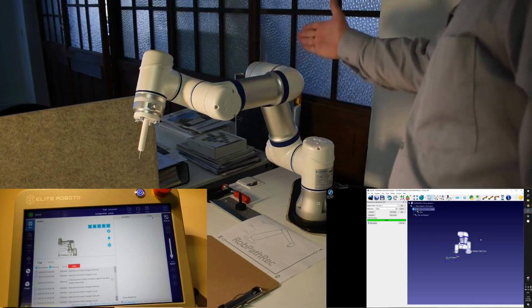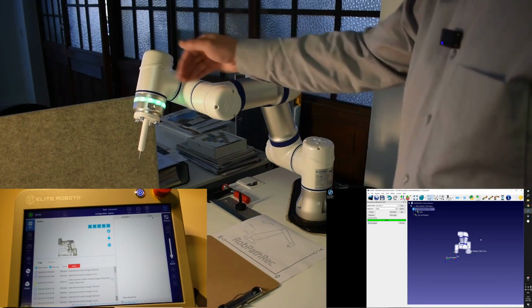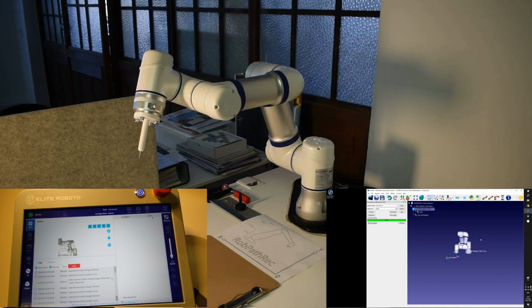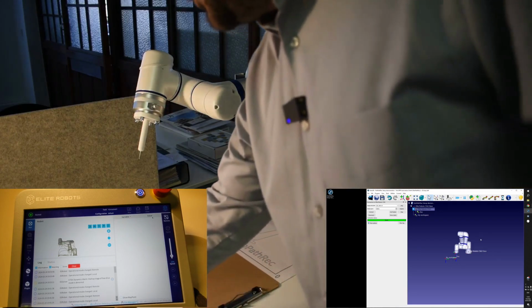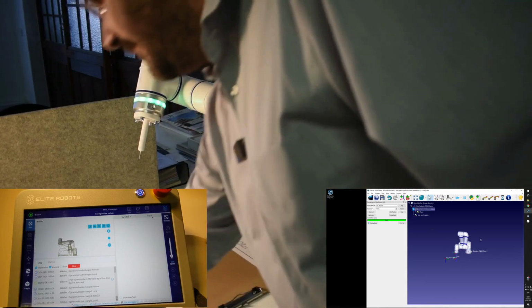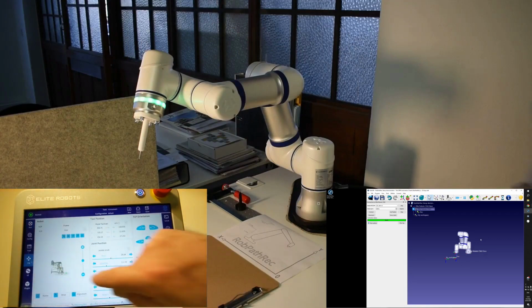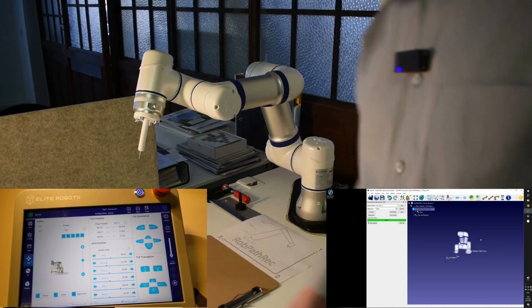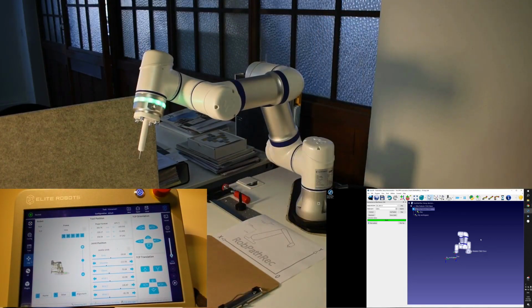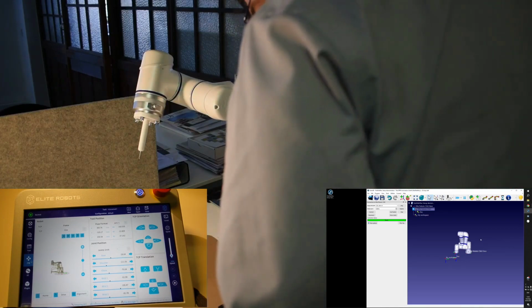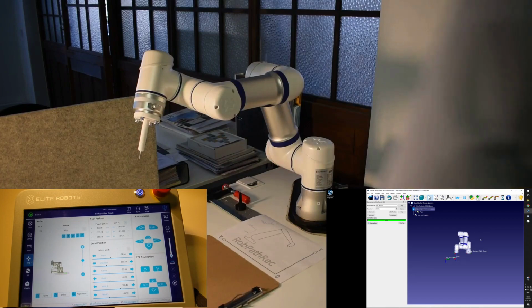If you would have this kind of very regular position, then it might happen that some robots will come into a singularity. So we recommend to come into a position, as you can see on the screen as well, which is not 90 or 0, so all of them are not straight numbers.